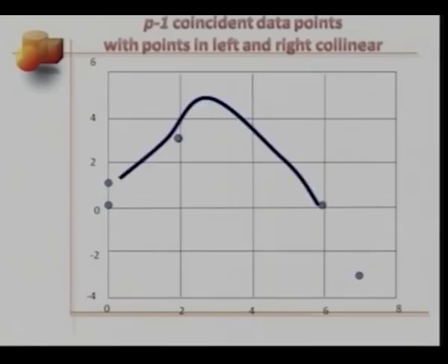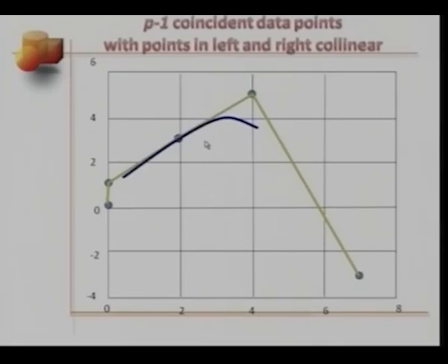Once again, we move this point here so that these 3 points are collinear, with this being a multiple design point. This is our new control polyline here, and this is the new shape of our B-spline curve. Notice that not only is the curve passing through this multiple design point, it is also tangent to it, rather tangent to the control polyline.